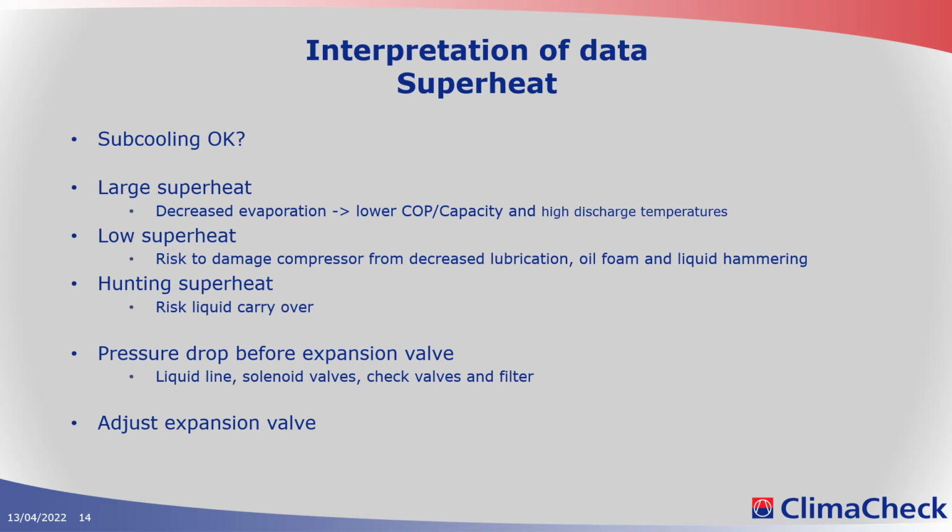So if I have tandem compressors or variable speed compressors or a different type of capacity change of our compressors, when I run at minimum capacity with maximum pressure ratio, that is when I'm going to have the most challenges getting a stable expansion device. So it's always good if you can check at maximum.